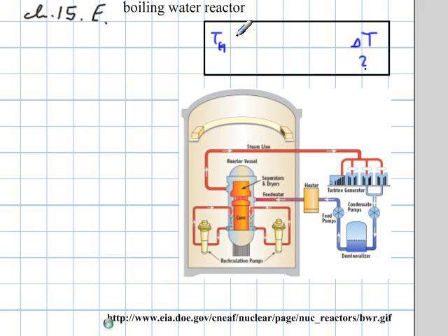And then the steam is going to go back to a cold temperature, respectively condenses to a cold temperature of 40 degrees Celsius. Of course, both of these have to be in Kelvin, so they're going to be 558 kelvins, top of my head, and 313 kelvins is what we need. It says that the plant operates at 3/4 of its Carnot efficiency. So at some point, I'm sure we have to determine its Carnot efficiency and then take 3/4 of that. The electrical output power of the plant is 1.2 billion watts. So that one is given.